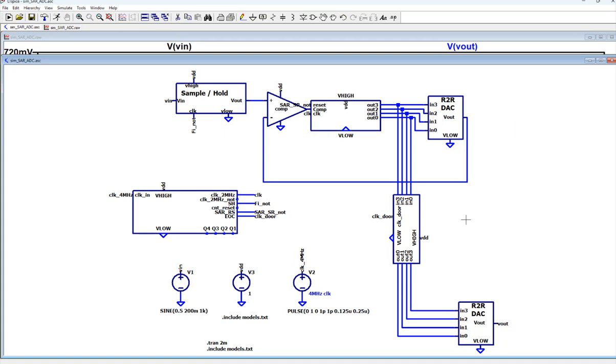It's parallel in, parallel out. Parallel in is going to the D's, parallel out are the Q's. Whenever it's ready, a simple rising edge will send everything over here to the other side. That's the data which is ready. You only want to send the ones that are ready to the output. But before it's ready, if all the D's are changing, are they affecting the result?